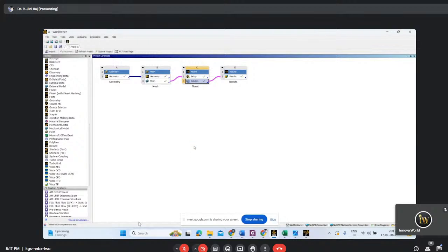Then for a different angle of attack, if you are doing like this, you can see here, I can duplicate this one. Easily we can duplicate. Once it is duplicated, you can give names also. Like 3 degree, for 3 degree angle of attack, what will be the lift we will get. For 0 degree, what is the lift we got? And now for 3 degree. Like that, for some 5 or 6 angles of attack you have to take. In a similar way, you will get the CL value and also the CD value.